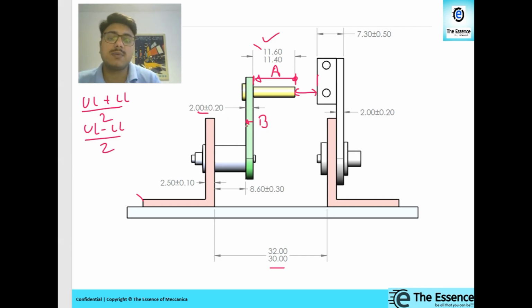So using that, I have reached this surface now. Now I can use this dimension to reach here. So I will be using that to reach the back surface of this L plate. That will be C for me. So A, B, C is there now, right? Do I need to use this thickness? No, I will not be using this, right? Why use that, as this dimension is directly given from there to there? So I will be moving from one surface, the back surface of the L plate, to the other surface of the L plate only. So that will be D for me. Okay, A, B, C, D I have, right?